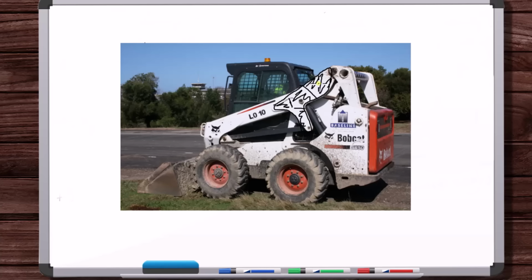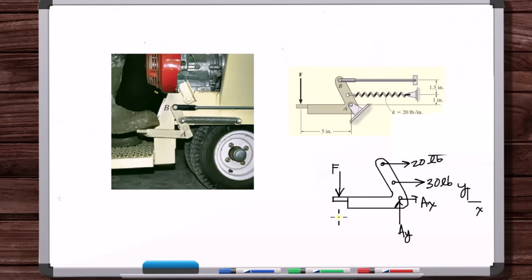Is that a rigid body? Well, the materials that something is made of makes no difference. That has no bearing on whether or not you're going to treat something as a rigid body. When the loads are applied to it, does it change shape? Does it change shape by any significant amount? We assume this force is vertical, right? We assume this force is horizontal.